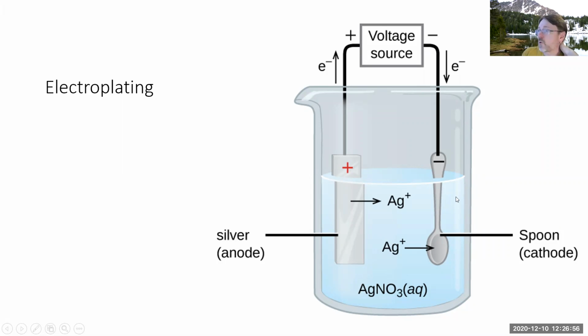You can coat most metals this way. You can coat with copper, you can coat with tin, you can coat with zinc, which we mentioned earlier is galvanizing. You can coat with gold. It's easy to get a thin coating of just about any metal, as long as there is at least some salt of it that you can have in solution. That's electroplating.